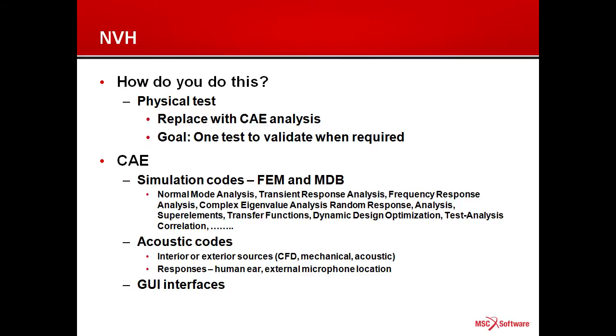The engine, which really is a big problem now, is because they've gotten things so quiet that now it's the powertrain that's a noise source. Direct fuel injection. The injectors, of course, run on high pressure fuel. Their opening and closing actually gives you a ticking type noise, which can be amplified when you go through a drive-thru. And the responses, obviously, your human error.